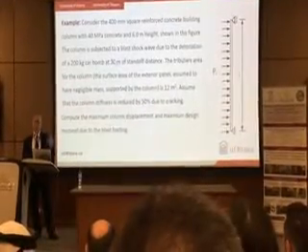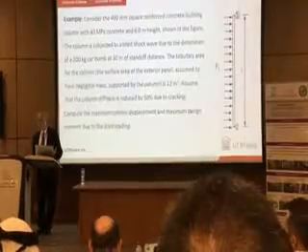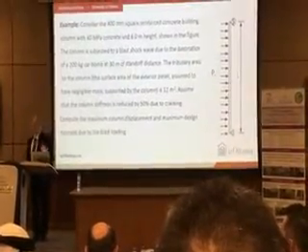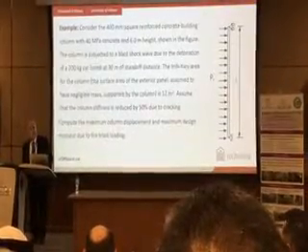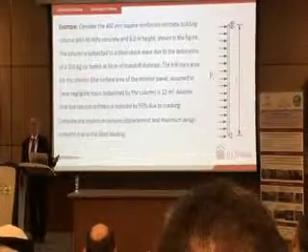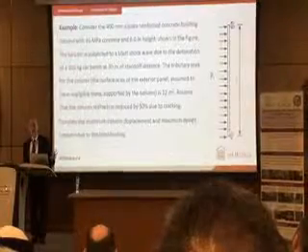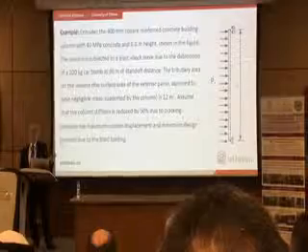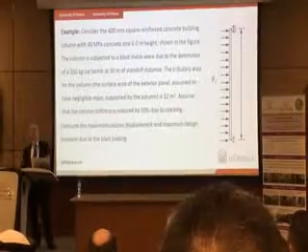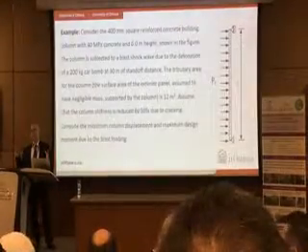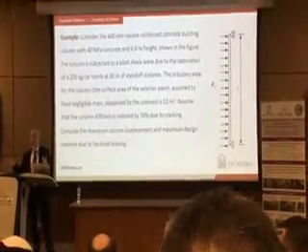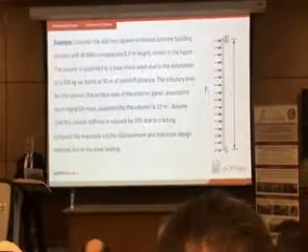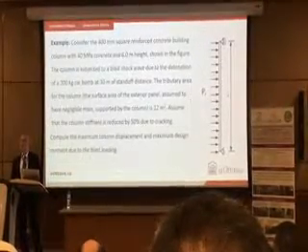So I immediately put in my software 200 kilograms and 30 meters and find incident pressure, reflected pressure, and duration. Or I could go to UFC charts, US Department of Defense charts, those wiggly curves, and get these quantities. So the first step is to convert mass of explosive and standoff distance to equivalent pressure and duration. Once I know that, then the rest is easy.